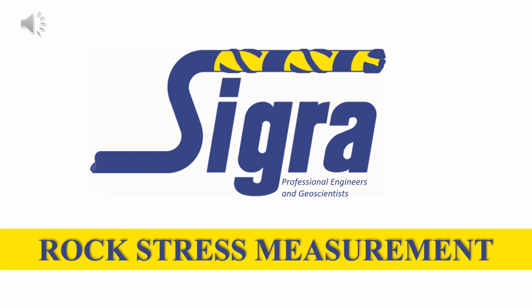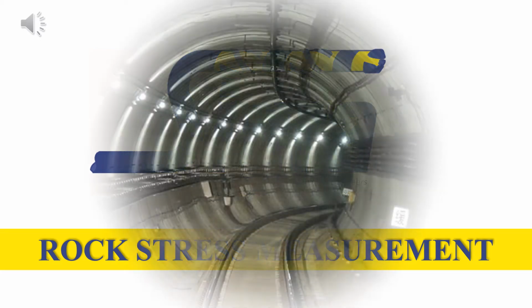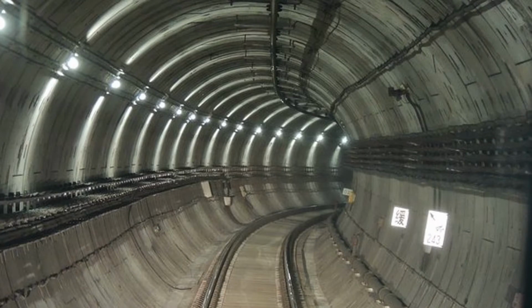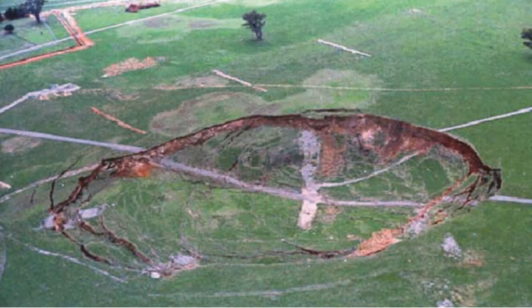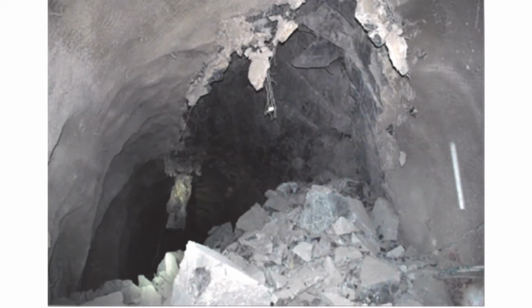Rock stress measurement. In combination with rock properties, rock stresses affect the way in which rock masses deform. This deformation may be required to be small, as in a rail tunnel. Deformation may need to be large, as occurs in mining using caving techniques, or as occurs in the collapse of a longwall goaf. Rock stress is also a key to understanding rock bursting and other larger seismic events.